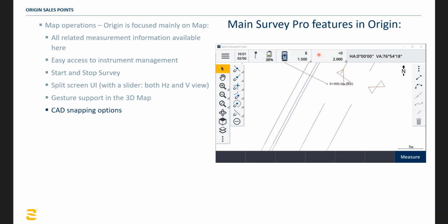So, for example, if we select here the intersection of the lines, it allows you to connect not only to really intersecting lines, but it will also allow you to do the extension of these lines. So now let's select these two lines, right? And then the software automatically creates the intersection of them, or the extension, if you would prefer.